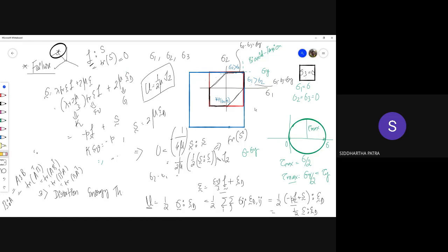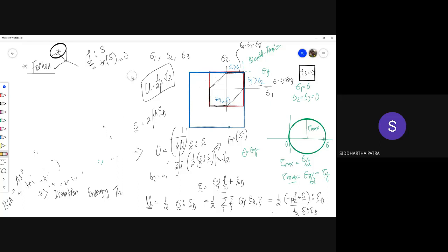Okay, so now look at the failure in shear. J2, we saw there are various representations. For example, this is one of the representations. Now consider torsion of a shaft or pure shear. So this is the Mohr circle. So this is your tau, and sigma 1 is plus tau, and sigma 2 is minus tau.